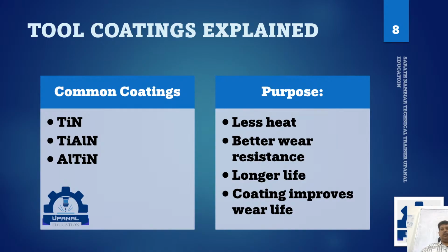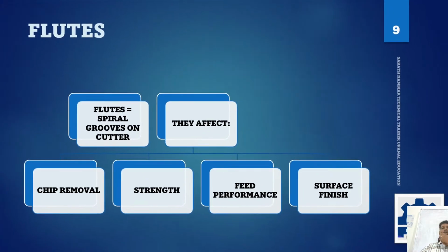But remember, coating does not fix wrong usage. If feeds are wrong or setup vibrates badly, coated tools can also fail. So we can say that coating is an advantage, not a miracle. When selecting tools, think of coating as one helpful factor among many.